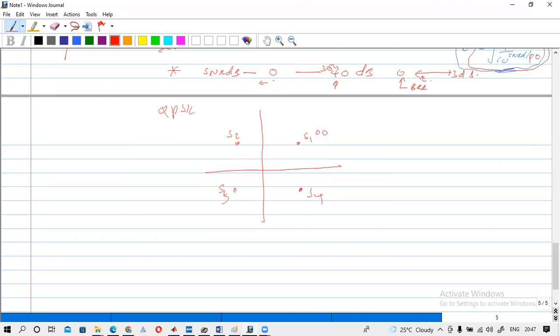Let's say this is 0,0, this is 1,0, this is 1,1. We have to use the Gray code here: 0,0, 1,0, 1,1, and here it should be 0,1. So it is Gray coding, and we assign bits like this using the Gray code method. So we have 4 constellation points, and you know that this value is 1 and this value will be 1.